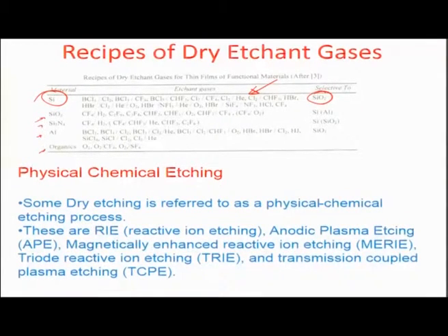This is also similar to a CVD reactor, where these gases are sent in at a controlled manner and interact with the surface, creating gaseous products of material coming off the surface, and thus etch away or engrave the material wherever the gases can attack.